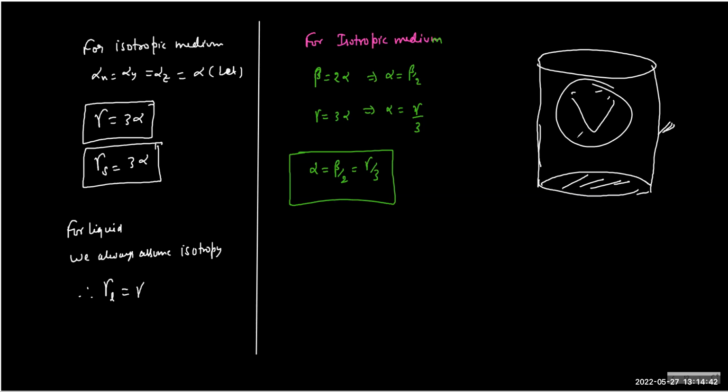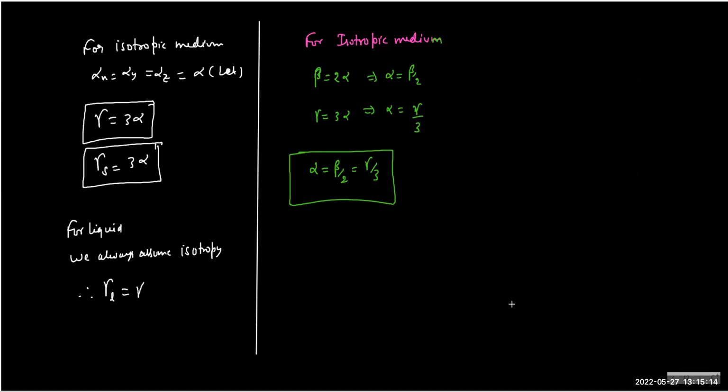When you cannot apply it is, if we have the upper portion made of some material and the base made of some other material, in that case we have to do the separate expansion and then calculate the volume eventually. So as long as you're solving a problem in which everything is made of a single material, then even if it is hollow, don't worry, you can think of it as a solid and apply the volumetric expansion formula. Okay. So keep this in mind, just in case you get confused at times.